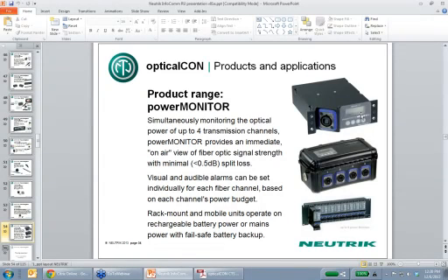It will monitor every fiber strand for the power in dBm. Now, dBm is the standard by which we measure optical power. So it measures every fiber strand. You can set programmable thresholds and alarms on this thing. So if any fiber strand falls below a threshold of power that you define, the box will beep and flash and let you know that it's time to do some cleaning or have some sort of problem.